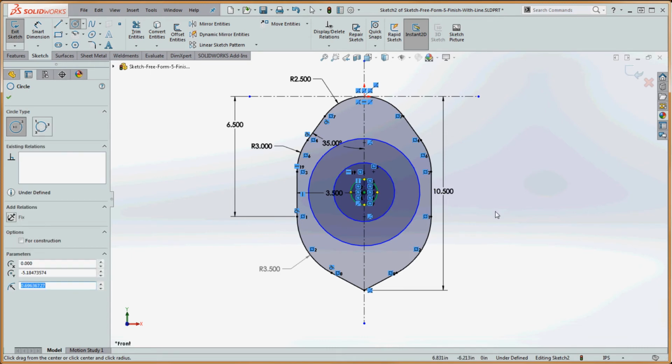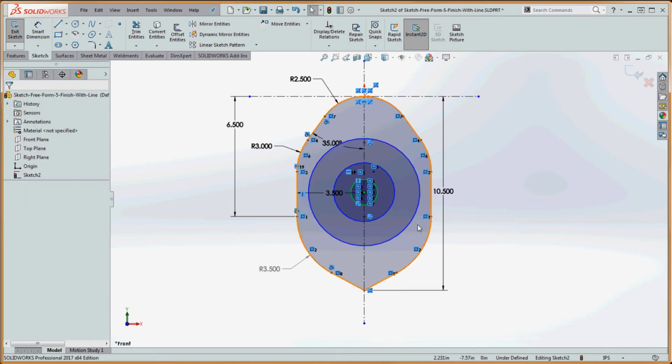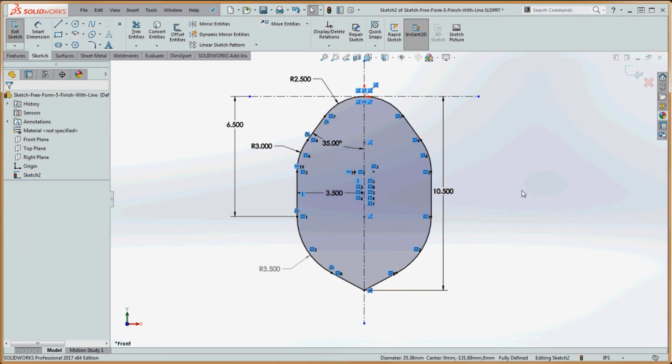So this would be a good time to use the contour select tool. If we're doing an extrude, maybe we click this outside structure out here for one extrude, this for another one, and that for another one, maybe one of these for a hole. If you want to see about the contour select tool, I have another video about that. But we're not going to do that. We're going to go ahead and delete each one of these circles in here, and that was strictly for demonstration to show you how SolidWorks lets you know that you do have enclosed geometry. So once you do that, we're ready to go.